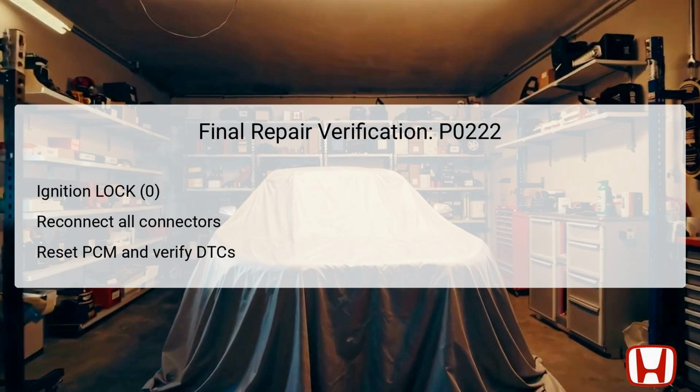Follow this by turning the ignition to the on position and resetting the powertrain control module, PCM, through the HDS. It is crucial to conduct the idle learn procedure post-reset for optimal engine performance. Finally, check again for any pending or confirmed DTCs.